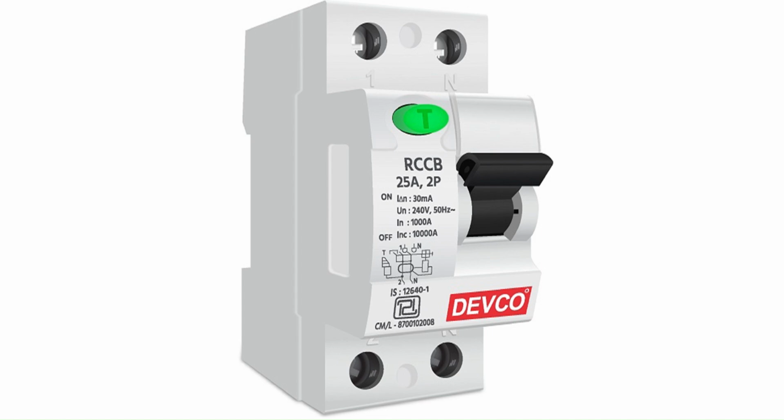RCCB is basically an electrical wiring device that disconnects the circuit whenever there is a leakage of current flow. It is the safest device to detect and trip against electrical leakage current, thus ensure protection against electrical shock caused by direct contacts. RCCB is generally used in series with the MCB, which protects them from overcurrent and short circuit current. It ensures 100% detection of leakage current and is able to sense the AC as well as DC leakage current.